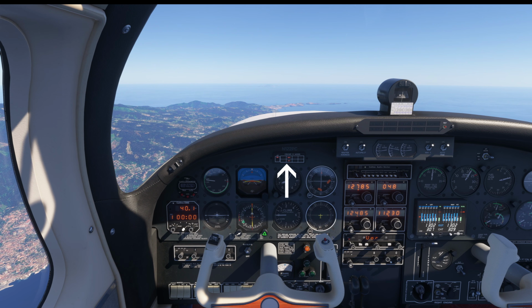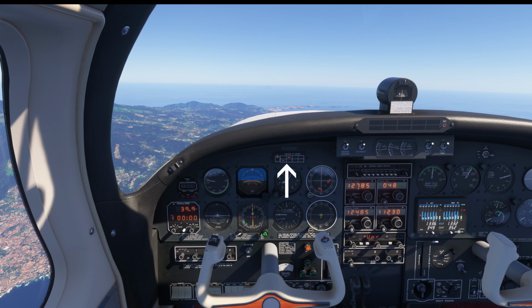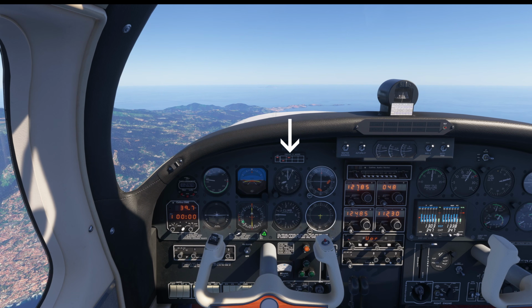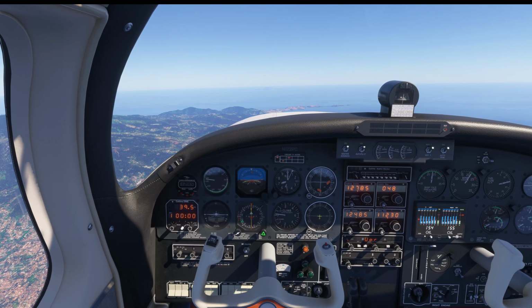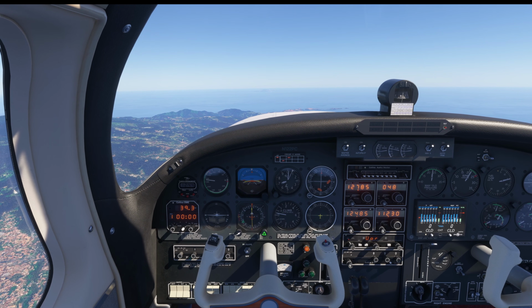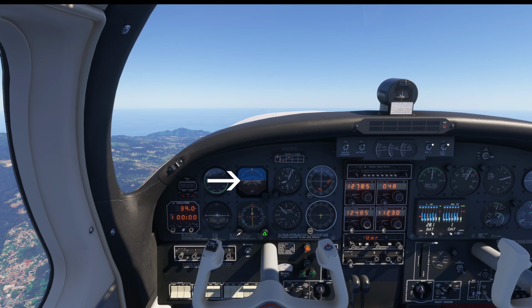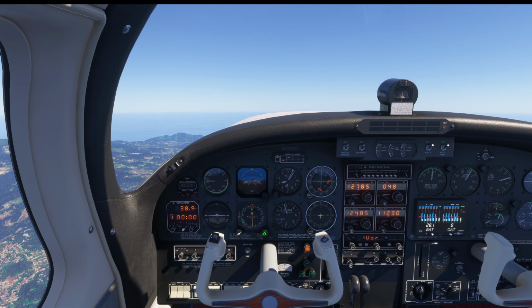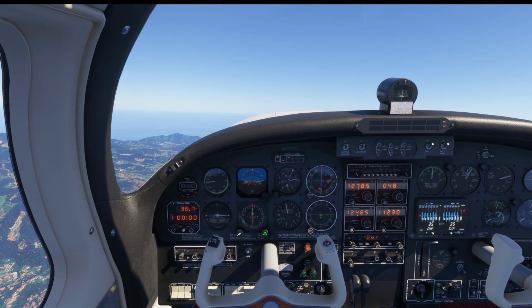When you press the pitch sync button, pitch mode will change to attitude, while lateral mode will remain unchanged. You will have control of the aircraft as long as you hold the button down. The autopilot will synchronize pitch reference to current aircraft attitude, and when you release the button, the autopilot will resume operation.